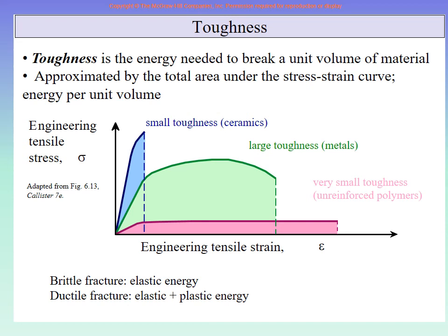So if you compare to previous, resilience is also toughness, but resilience is the elastic toughness, right? Resilience is the toughness in the elastic region, and toughness, just toughness, is the toughness of the full curve until fracture. So this is the resistance of the material, but this is an energy now, right? They say stored energy, amount of work. So if the material is brittle, it will have only elastic energy, there will be almost no plastic deformation.